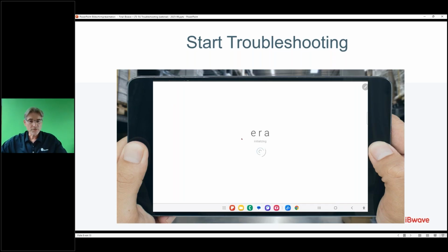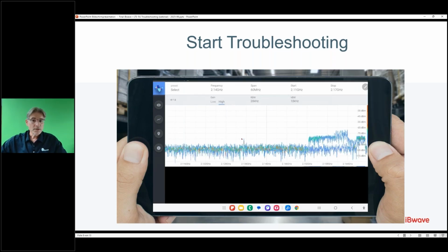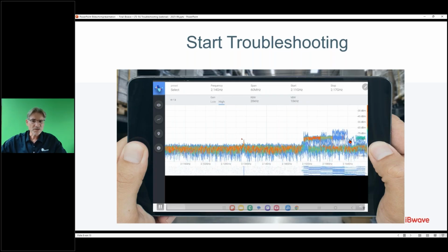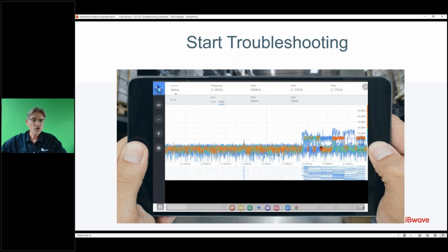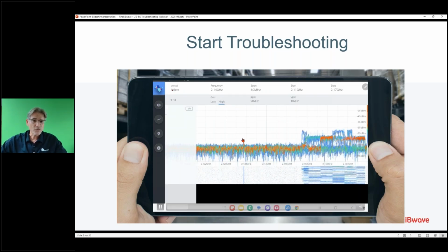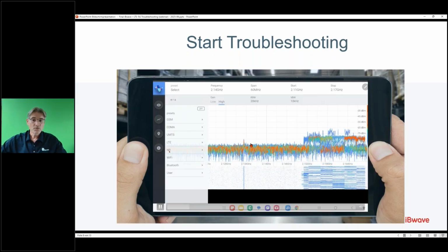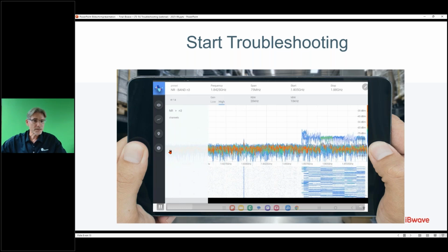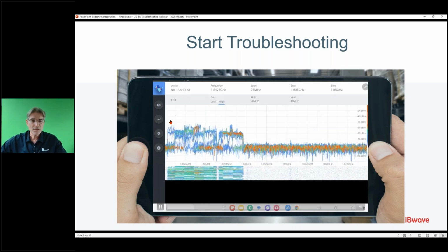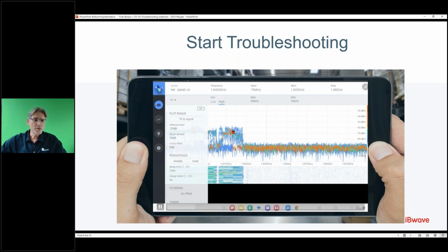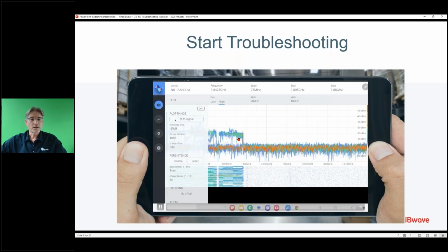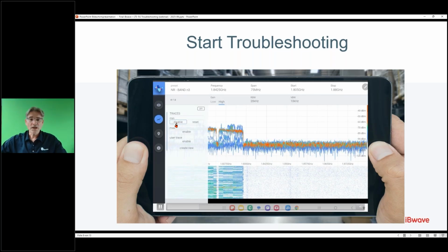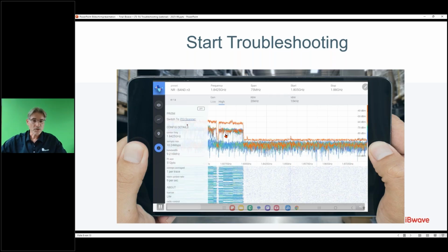And once you have the spectrum analyzer running, it will show you immediately the frequency bandwidth and the signal strength, so it gives you all the information if there's any interference from any other signals which could create problems. You can switch to different frequency bands like 5G, LTE, or any other technology, and it immediately will give you the spectrum. And you have with the spectrum analyzer all the features of a standard common spectrum analyzer.